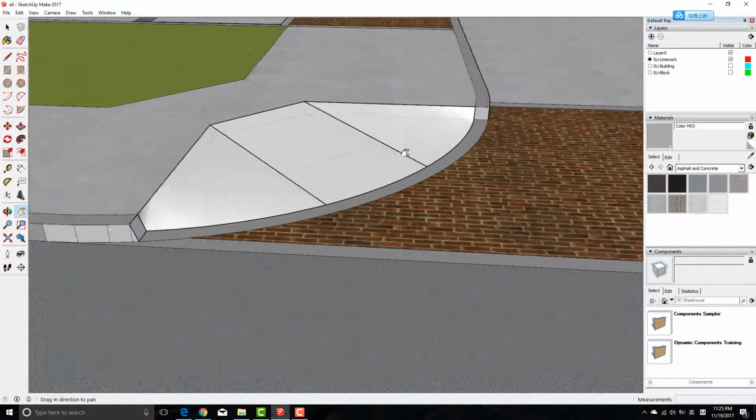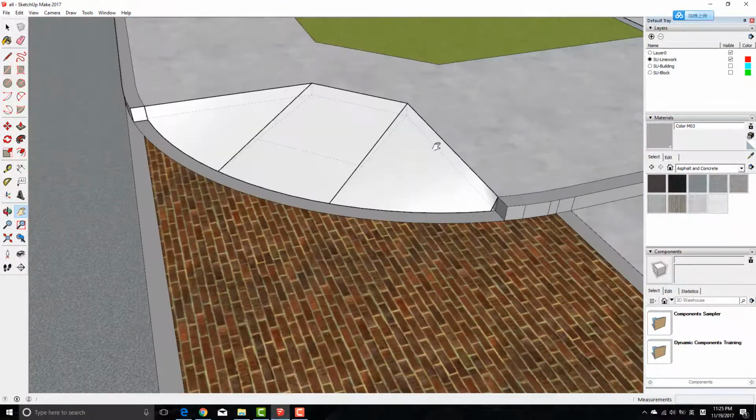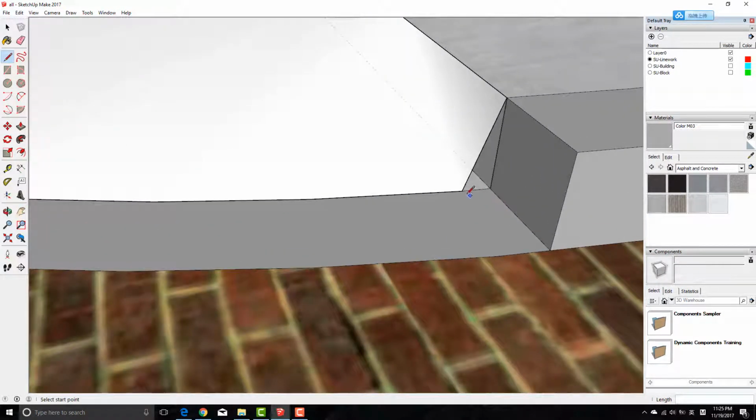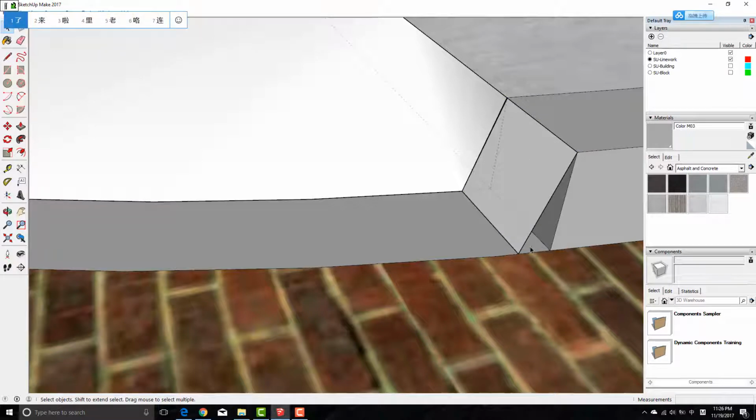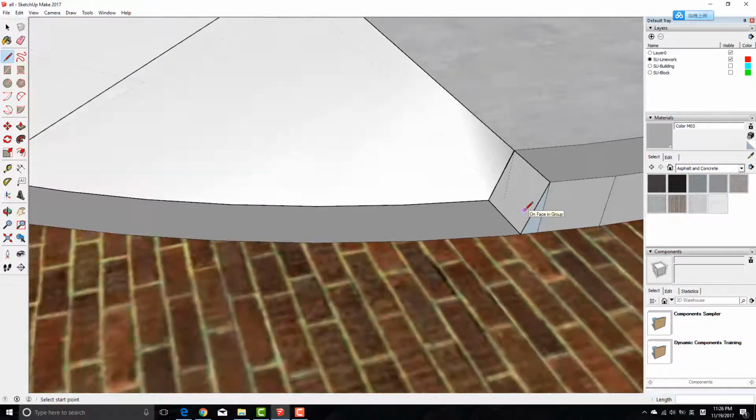So I will do the same steps here. So draw a line first along the red axis. Select the bottom line and top line. Click Draw, Sandbox, From Contours, and use Line tool again to generate face. Then I will give them different colors and materials.